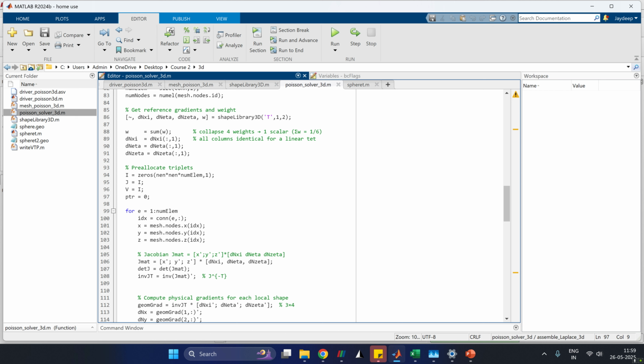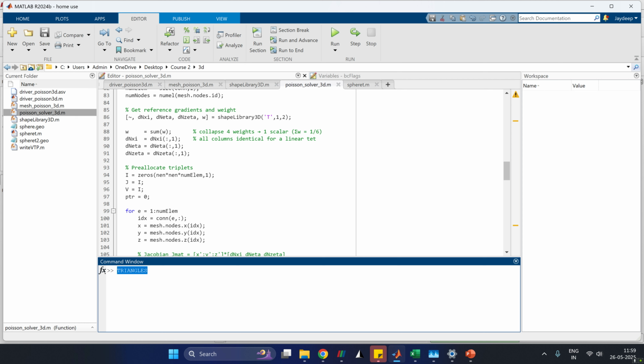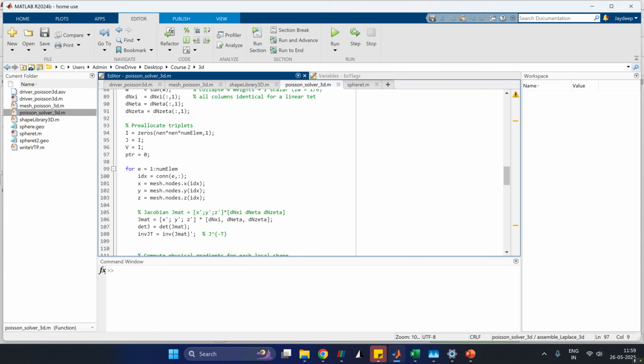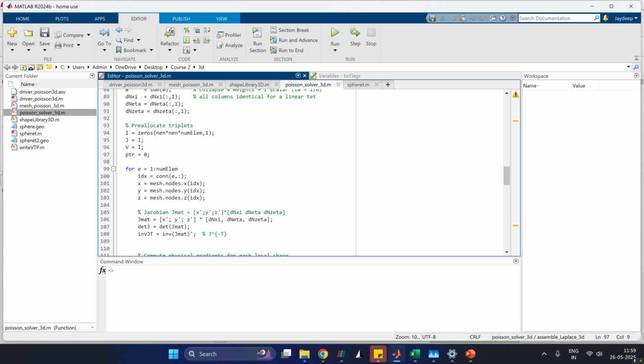This will allow us to run larger meshes, because in the live coding I did not do a sparse assembly, which uses a spalloc kind of command, or triplet assembly. Those are the two ways to do this in MATLAB. In case of Python and Julia also, I'm not aware if there is a spalloc kind of command, but you can do these triplet assemblies anyways. These help you to run the solver to much higher mesh densities. So that's the structure we have used here.